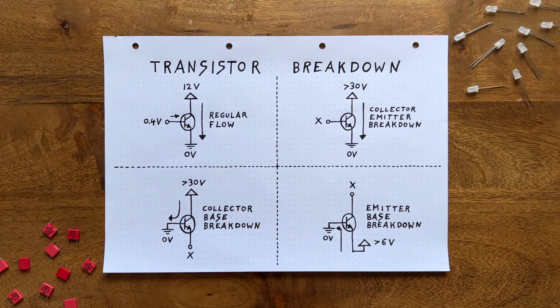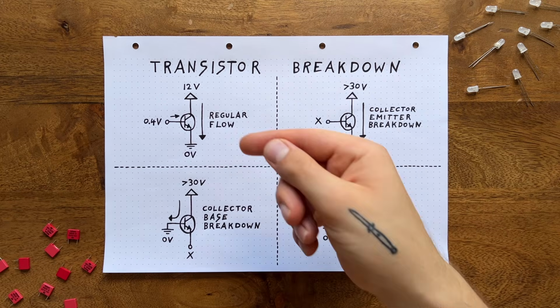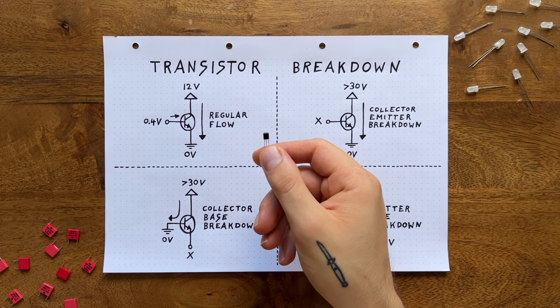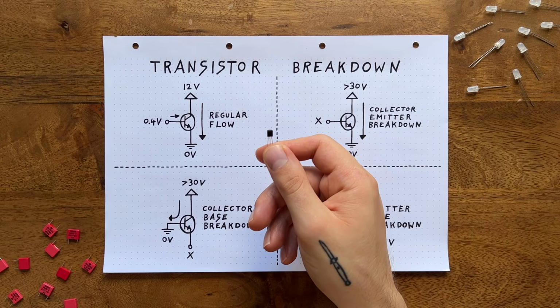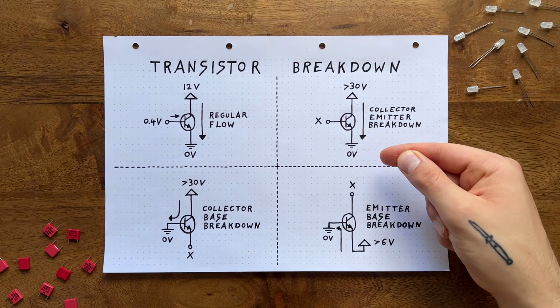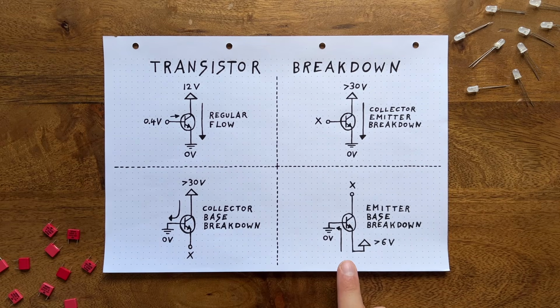As you might already know, the deal with semiconductors is that they only allow for current to flow under certain conditions. For an NPN transistor, it works like this. No current can flow into the collector as long as there's no current flowing into the base. At least in theory. In practice, if we check the datasheet for this BC548 transistor, we'll find multiple mentions of something called a breakdown voltage. There's one specified each for the paths between collector and emitter, collector and base, and emitter and base. What does this mean? Simple.